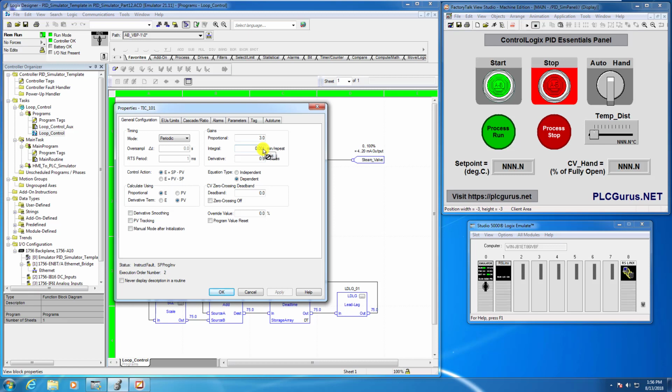We were at 0.01, which I thought had a nice smooth response, a nice fast response, and then we added a little more integral by making the integral gain component here a bit smaller, and we saw that we started to get a little bit of overshoot, and I think we were a little bit too rigid. But anyhow, we still had a nice, stable, fast response. And of course, we left the derivative at 0 for now because we are implementing this as a PI controller.